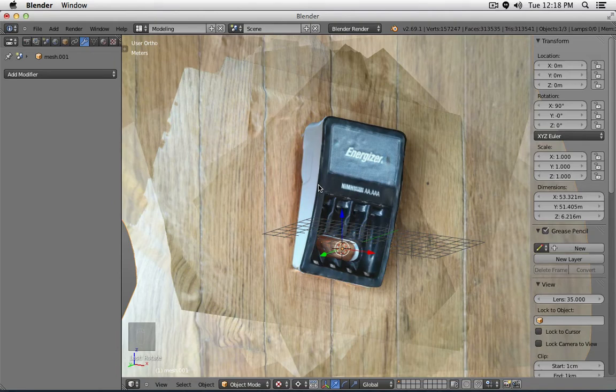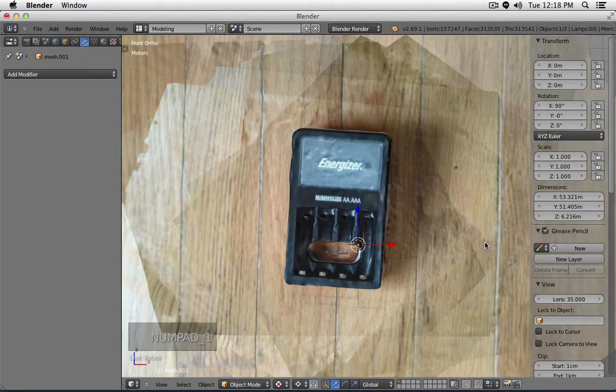You can use something like dry shampoo. If you get that spray can, it works kind of like a starch material. So you could basically coat the plastic with the dry shampoo, and then it's brighter. The shadows will be better to see, what is in highlight, what is in shadow, the way the light illuminates the surface will be easier for the software to see, and that will actually generate a better scan result.